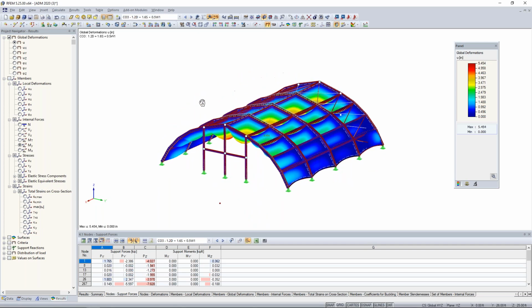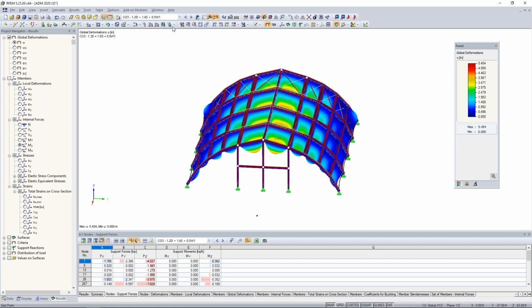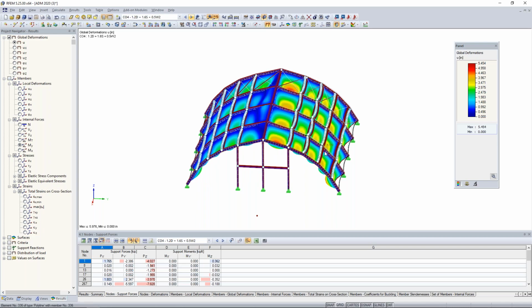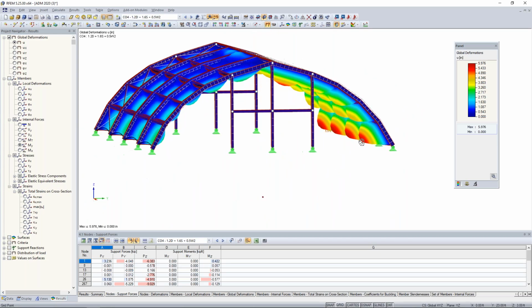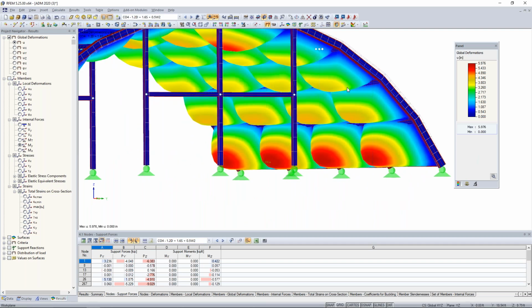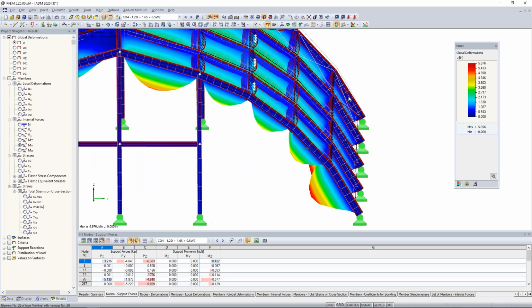And you can see in this downward deflection, as I talked about, and we'll see this with the following load cases as well, that when we have pressure here on our fabric membranes, these truss elements we can see on the other side are going to catch it. So we have that full integrated behavior between those truss elements and the fabric membrane.